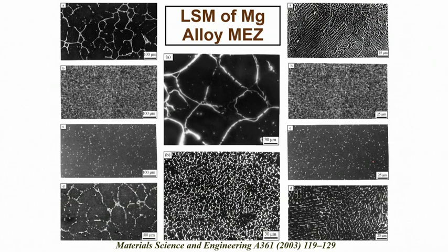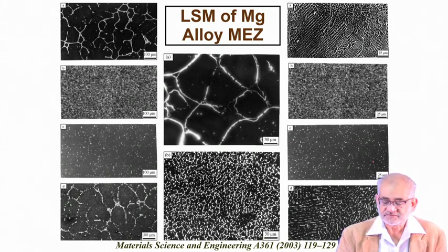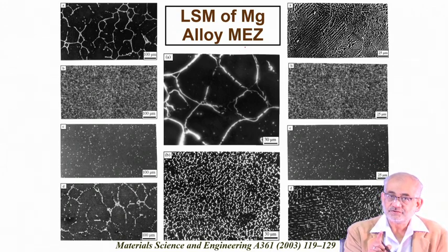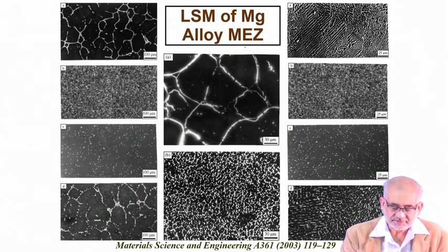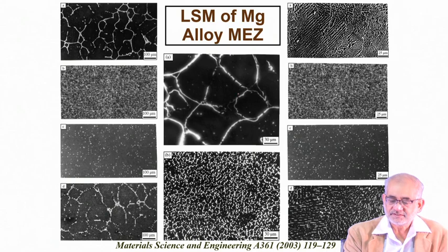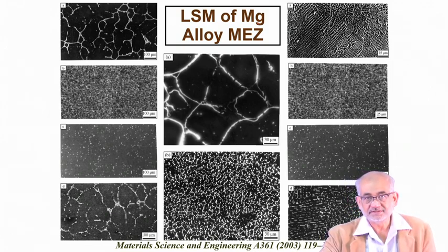In order to understand that, these microstructures are derived from components subjected to various kinds of laser surface engineering routines. But in the previous two cases, I emphasized that we should remain below the solidus temperature. That means we don't want formation of liquid either in small volume or large volume, because liquefaction followed by solidification will create residual tensile stress, which is what we don't want. But if we are dealing with magnesium or aluminum alloys, such low melting non-ferrous alloys, we can easily melt the surface.